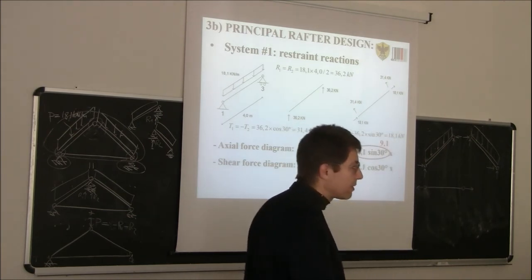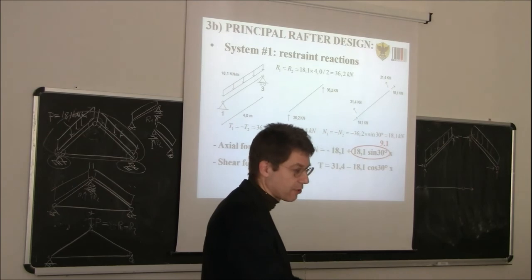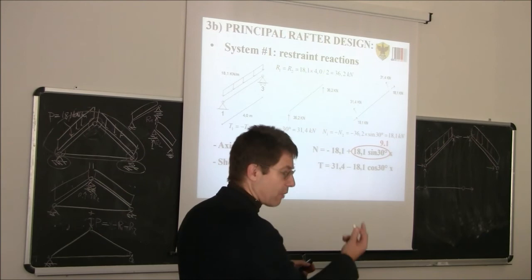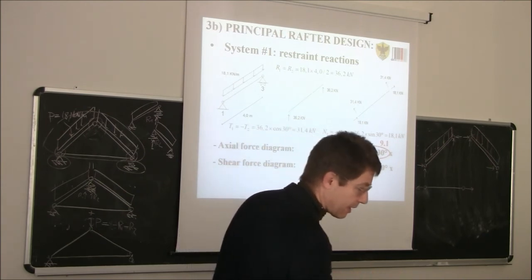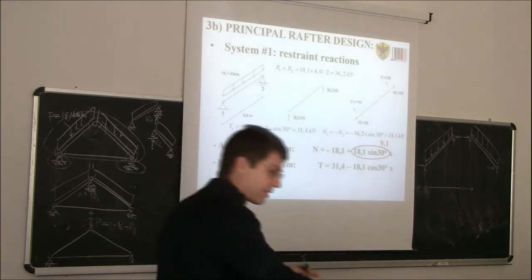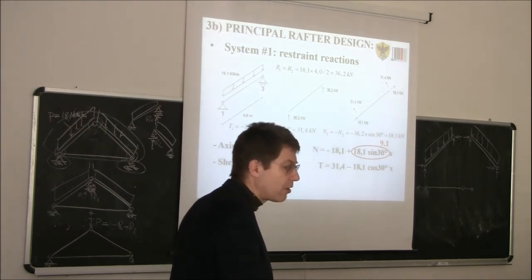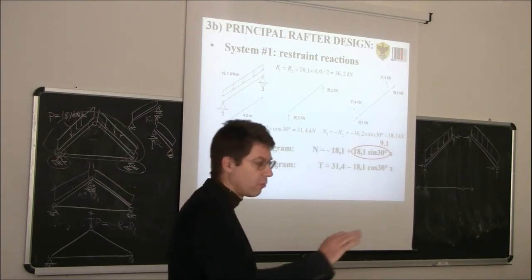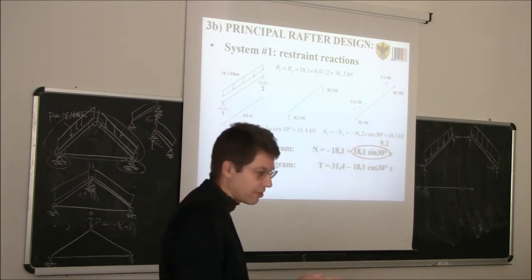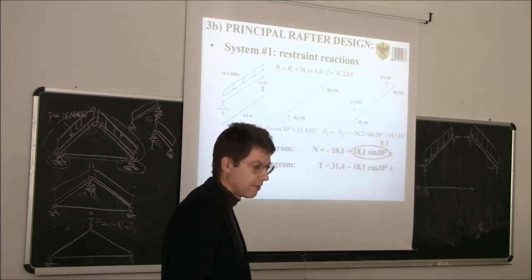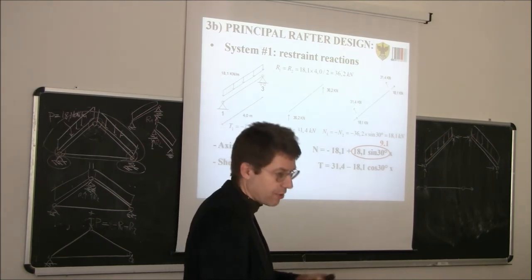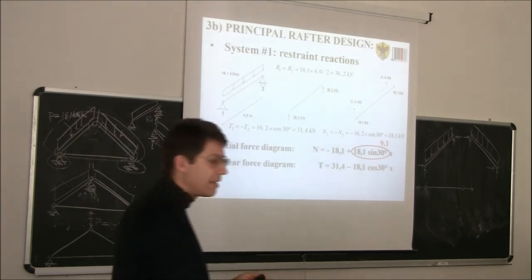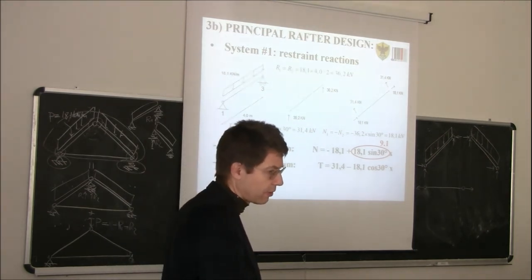On the shear, there is a slightly different convention in mechanics of structure and in structural design. Usually in structural design, the shear is positive in one direction, but I know that in mechanics of material, we learned that it's positive in the opposite direction. Okay? Anyway, the sign of the shear is not important. So you can use one convention, you can use the other one, nothing changes. The sign is important for compression, tension, so axial force, and it's important for bending, not for shear. So for shear, you can use any kind of convention that you want without any problem.